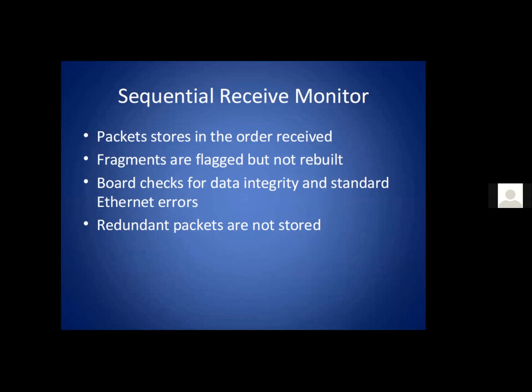So here you might be better off with a sequential monitor. What a sequential monitor does is it takes every packet that comes in, time stamps the packet, puts it into a buffer, and it's ready for you to read. And you can read every single message that came in, in the order that it came in, not divided by VL, but all of them in the same place.